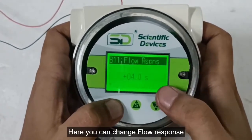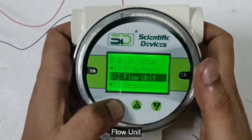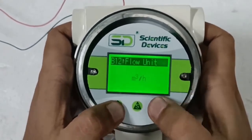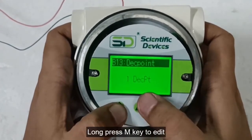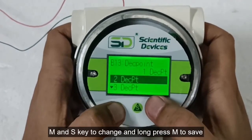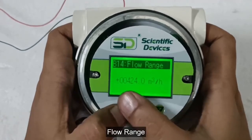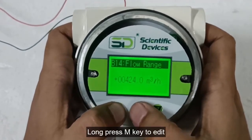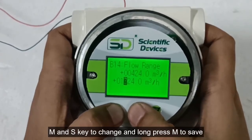Here you can change flow response, flow unit, decimal places to display. Long press M key to edit, M and S key to change, and long press M to save. Flow range. Long press M key to edit, M and S key to change, and long press M to save.